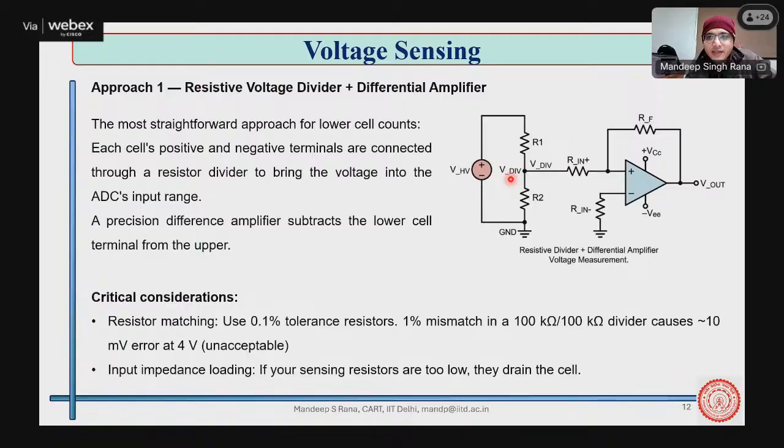So what we do is we have some voltage being sensed, which is more like battery voltage, and then a voltage divider. Through that divider, it is generally op-amp based, because differential means we are sending data which has nearly the same voltage. It helps us cancel out noise or signals which are present on both terminals, and it helps us amplify the data.